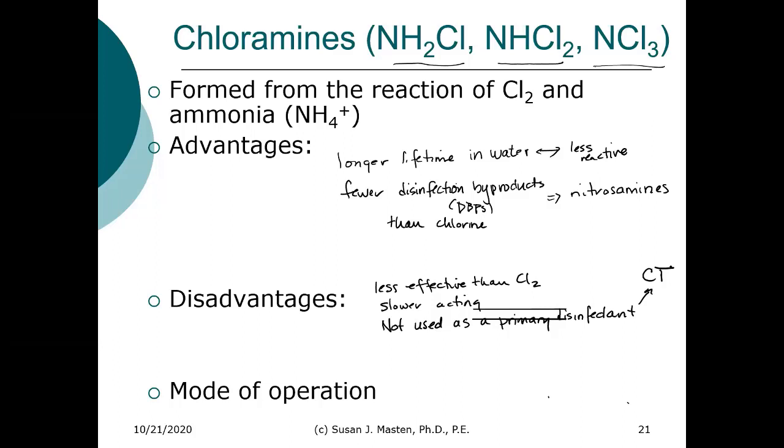The other problem with chloramines, it can change the redox chemistry. It's a more reducing environment, and that has been shown to cause problems with the release of lead.